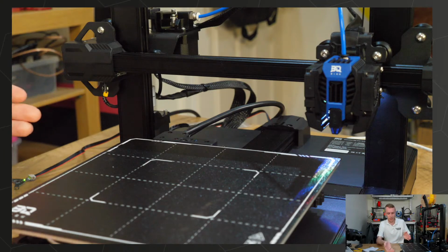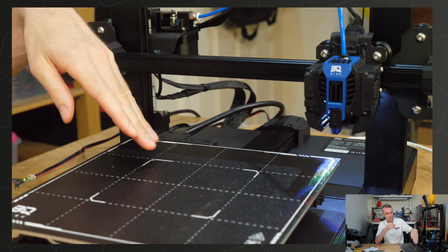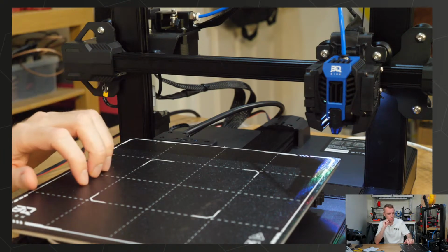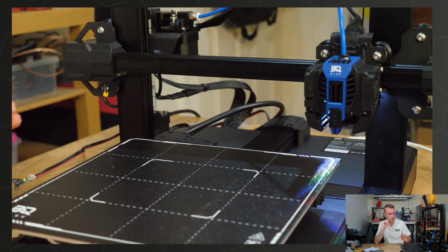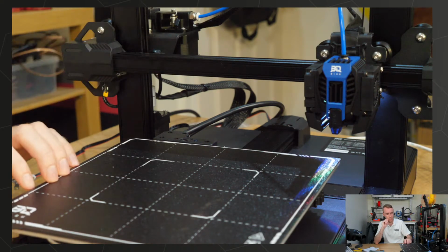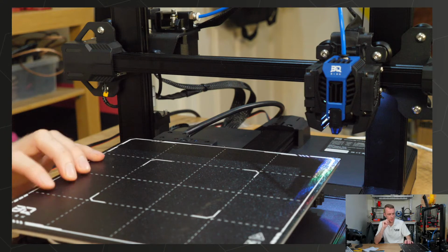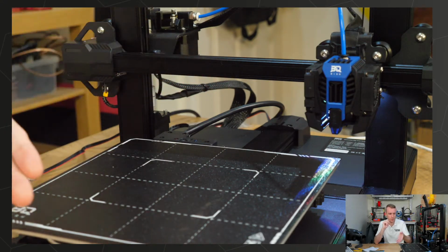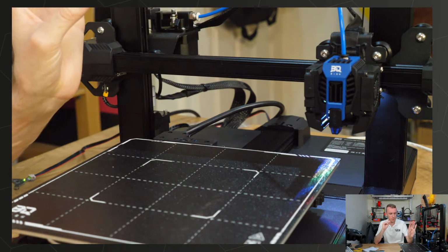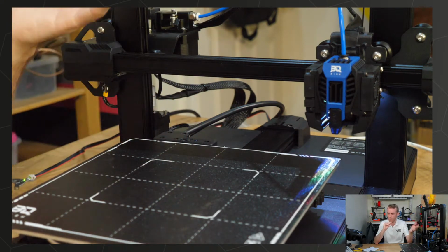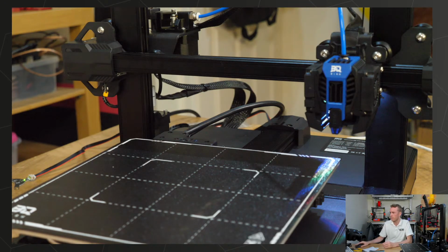Because in Klipper we set acceleration for both axes simultaneously, and the Y axis is much closer to its limit because it's much heavier, we can set this one to stealthChop, I think, and this one to spreadCycle, because this is quieter than this. So we should be able to achieve similar noise levels, but with this one on spreadCycle, which should maybe increase the performance very slightly. We might be able to get slightly higher acceleration.